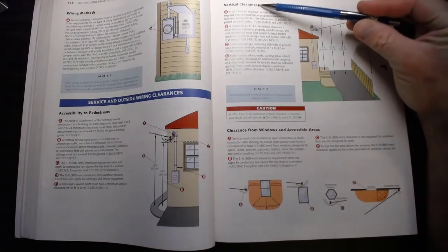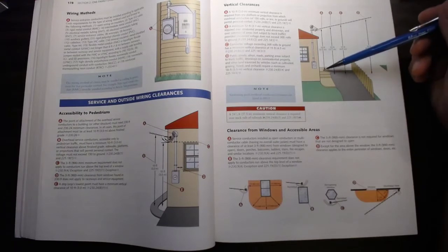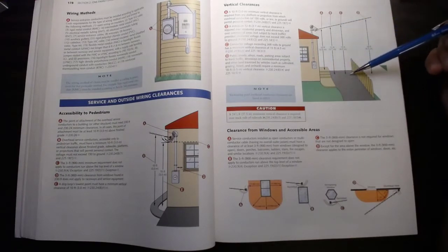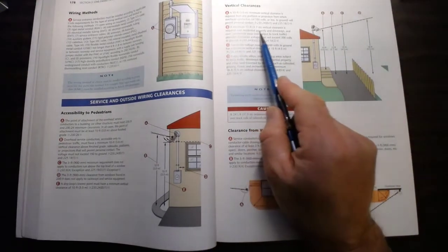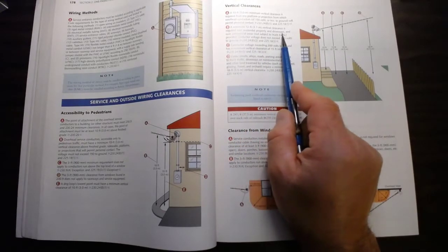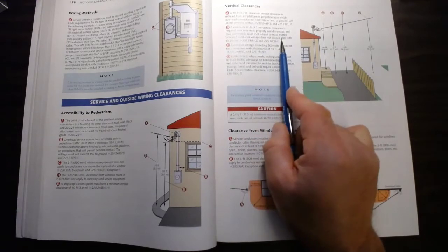And we look at vertical clearances here, and we're over different types of locations. We're over stairs, minimum 10 feet for pedestrian. And then we have driveway, and we have a going out farther here into the street. So when we look at B, it says a minimum of 12 foot of vertical clearance required for residential properties and driveways and over commercial areas not subject to truck traffic, because trucks are taller than 12 feet.